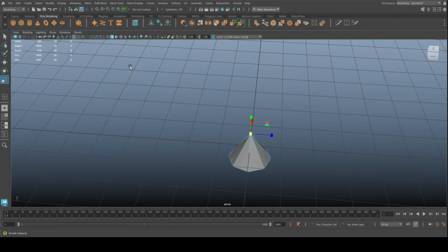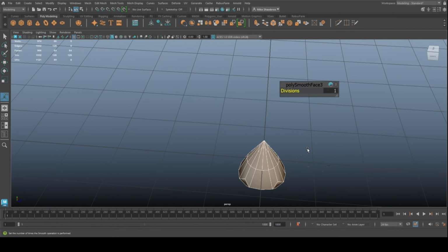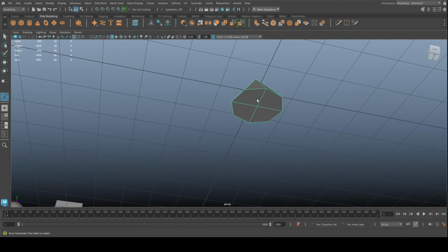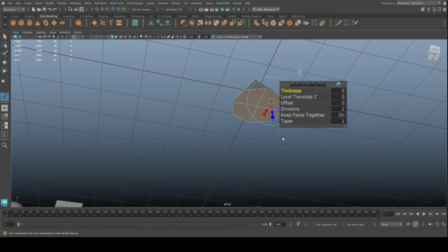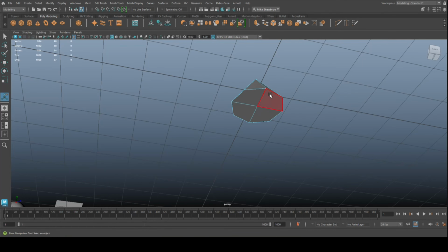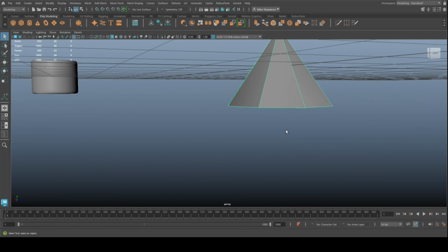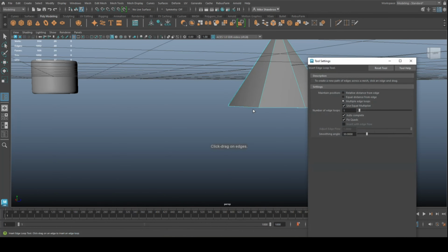We're going to go up, right click, object mode, mesh and smooth. We need to add an edge loop on the bottom there, and you can either do it this way: grab these, we're going to set the offset to 0.001, hit 3, and if that isn't enough, you can go in here and add one at the bottom, right?